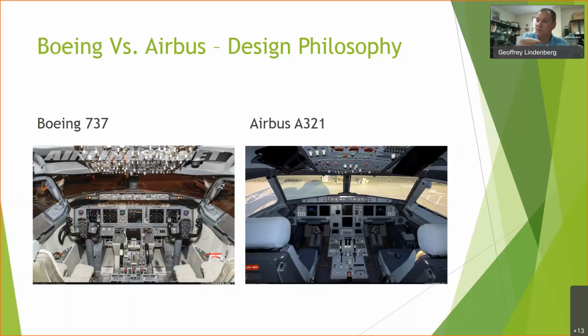And so you can pull back on that stick as hard as you want under normal control mode, and the airplane will pitch nose up until it gets to just before it would stall. Then the fly-by-wire system and the AOA vanes and everything, and the auto throttle, the engine thrust level, are going to hold the airplane at that nose up just below a stall. It's not going to allow the airplane to fly into a stall.